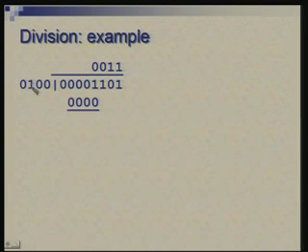We are now targeting a 4-bit quotient. We have a 4-bit divider, and if we are able to subtract 0100 in this position, then it will result in a 1 here, but in this case we cannot, because this is larger in this position. We are only subtracting a 0, and we place a 0 bit as part of the result.